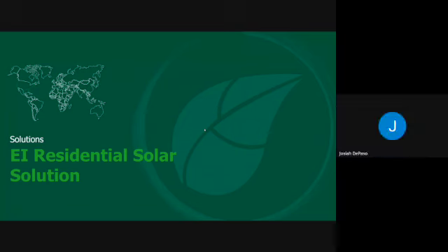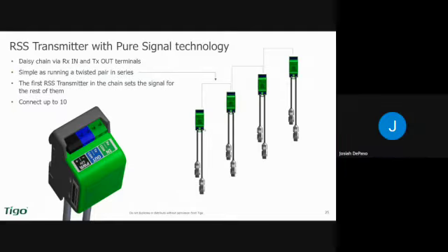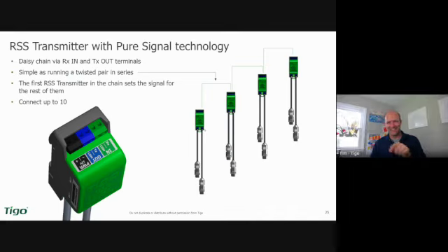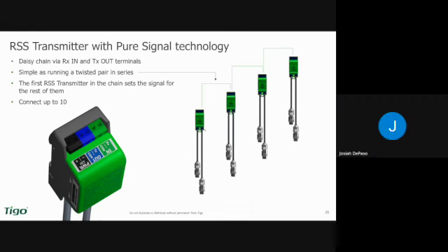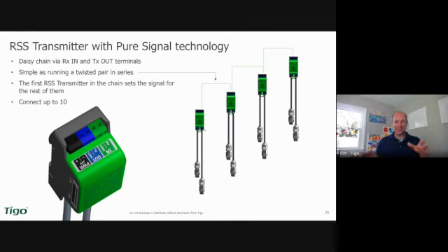All right. Listen, that's kind of similar to how you have to have a separate comms conduit from your DC cables and whatnot, so you don't get... I gotcha. Exactly. Yes. And here's where I didn't want to get into too much of the weeds there, but that is exactly it. You start to put things together, things bleed, then unfortunately things start to fail, and we're here to help, right? Nobody's doing it maliciously, but when it's installed the wrong way, there can be adverse effects. Yep.